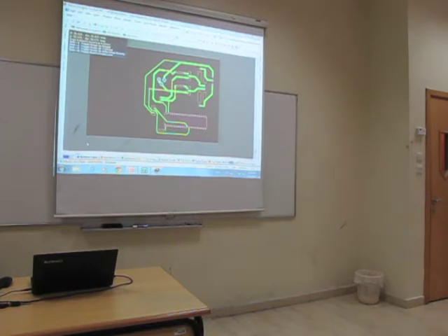Even this one is not suitable, so they use new laser technologies that activate the boards and create copper on them. Then it needs some complicated testing, for example X-ray testing. When you have lots of layers, you cannot visually see what's in between, so you need X-ray to see what's going on.